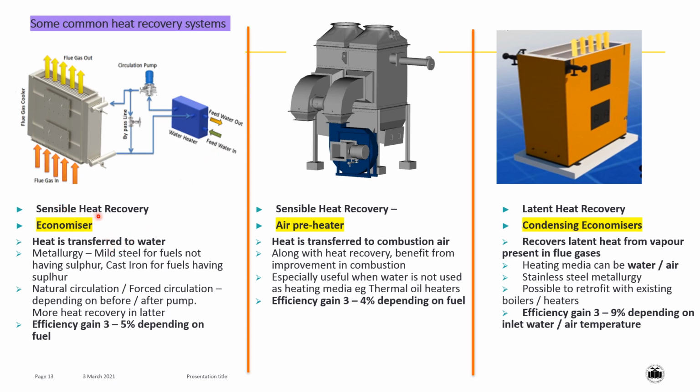In this, sensible heat from the gases is recovered. There is a gain in efficiency by 3 to 5% in economizer depending upon type of fuel used.